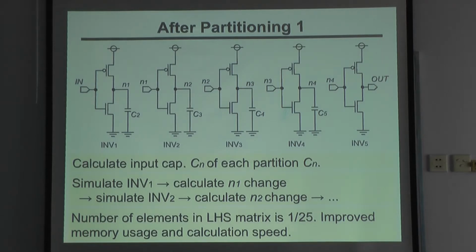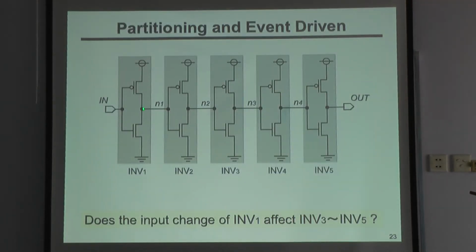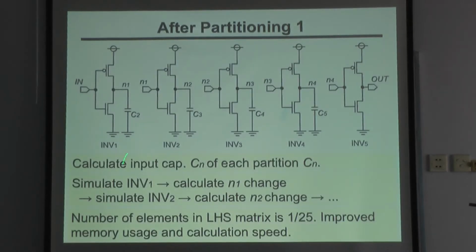So what they are doing is calculating the input capacitance of each stage, converting it into one capacitor like this, simulating inverter 1 and calculating the N1 change, and then simulating inverter 2 and calculating N2.